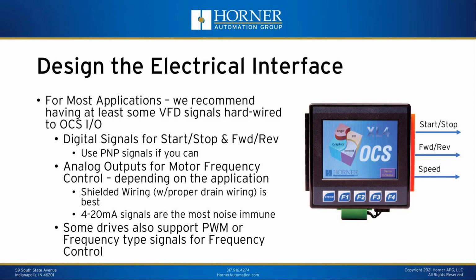Another thing that you'll find from time to time is for controlling drive speed or drive frequency, some drives also support a pulse type input, often in a PWM format where it's looking for a fixed frequency with a variable duty cycle, or maybe even in some cases where a variable frequency on the input signal will cause the frequency of the motor to be changed in a proportional fashion. So that's another option you'll sometimes see in the case of controlling frequency from a hardwired signal as an alternative to an analog signal.